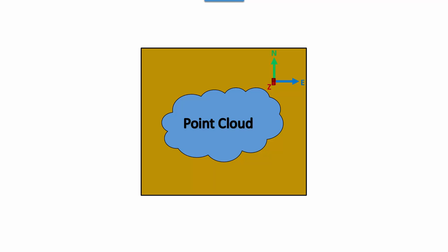And the purpose for this is to allow the user to now have a two-dimensional view of the point cloud data to provide ease of use for generating CAD deliverables. As well, this can be exported out as a georeferenced image or a DWG file for use in a CAD package. Now we'll look at an example of creating the orthophoto in TBC using a point cloud dataset from the